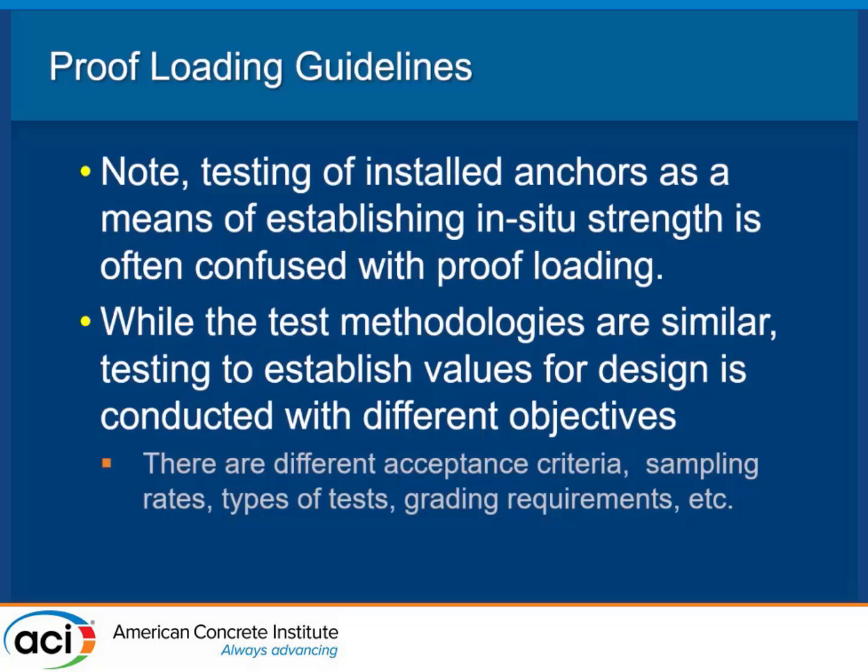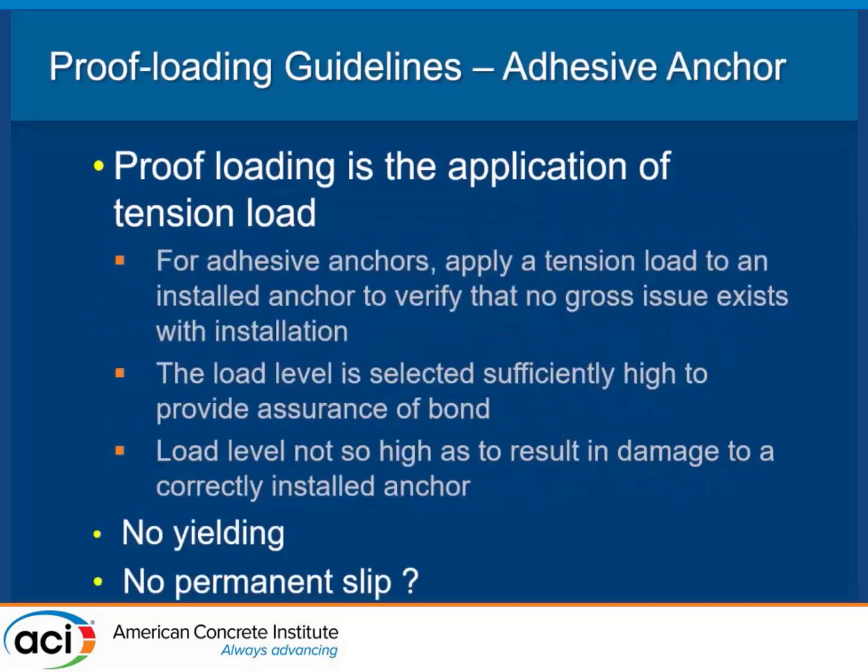And so you hear about proof loading a lot. So I kind of threw this in there a little bit. What do I do if I want to proof load? What proof loading is, is we just want to make sure that the anchors were installed well. We're not trying to establish that these things can handle the maximum load. That's not the objective of proof loading.